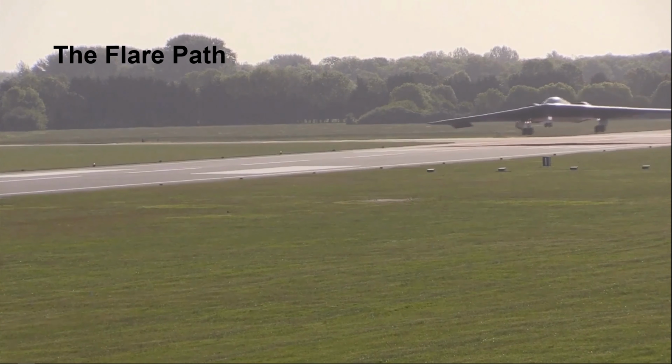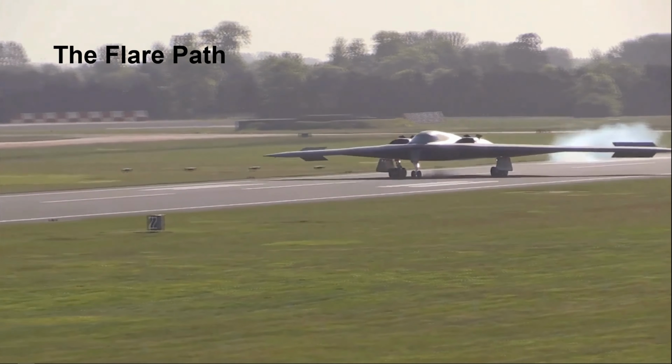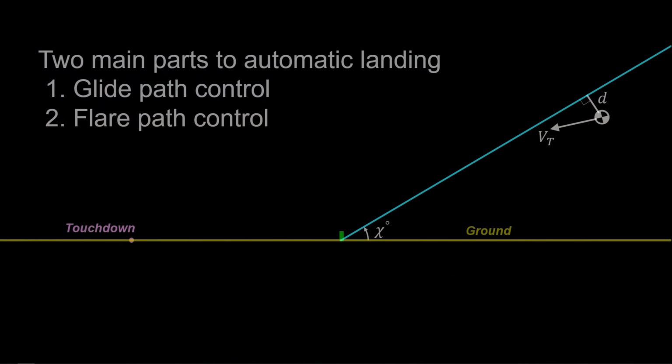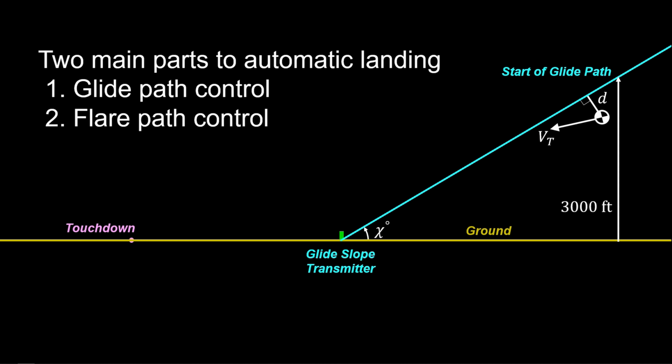Automatic landing systems must reduce the rate of aircraft descent for safe touchdown. This is the final phase of landing, called the flare path. The flare path is the second of two phases in automatic landing control. In the first phase, known as the glide path, the aircraft controls its velocity about a transmitted glide slope from the runway. Closer to the runway, the aircraft transitions to the flare path, where the rate of descent is slowed for safe touchdown.